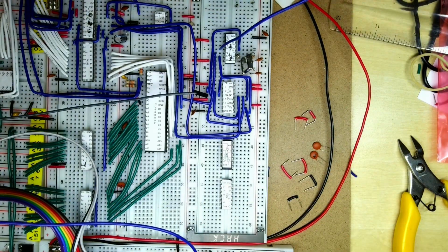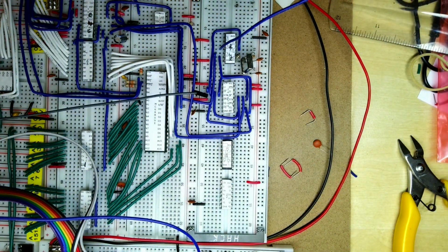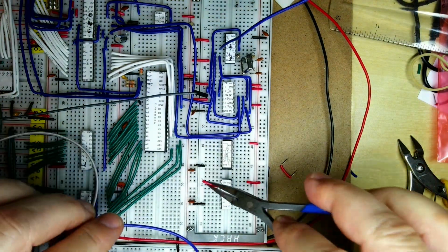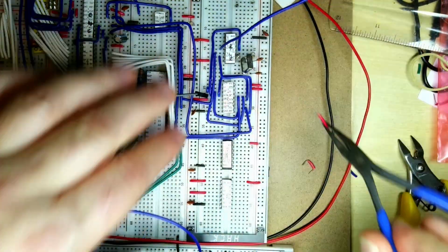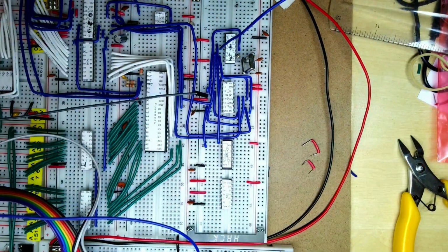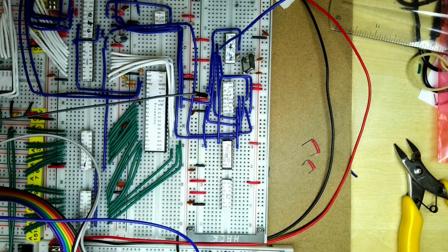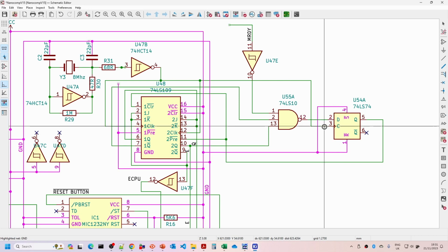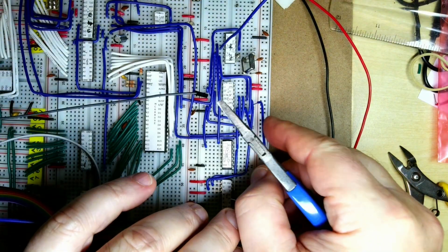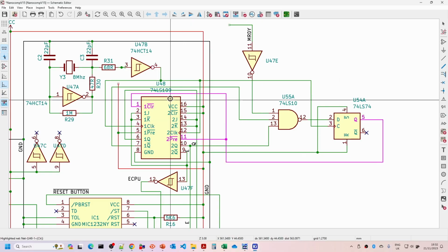Just plug the chips in, and we'll put in the power lines and the decoupling capacitors. Then we're going to take the 3 input signals down to the 3 input NAND gate at the top of the first chip there, and remove some of the pull-ups and put new pull-ups in. So that's the first of the leads into the 3 input NAND gate. Then we need to check those off. Then we've got the output going into the latch there. Then we need to check the clock signal, and so the other Q signals, and then the feedback.